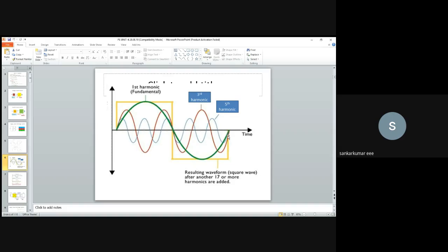So that is also an AC. Alternating current means alternating positive and negative supply. So here we are having positive and negative half cycles in the form of a square waveform. But we have to obtain a pure sine waveform as the output, so we have to extract the sine waveform from the output voltage waveform. In domestic applications, in houses also, you can see the inverters as pure sinusoidal inverters.